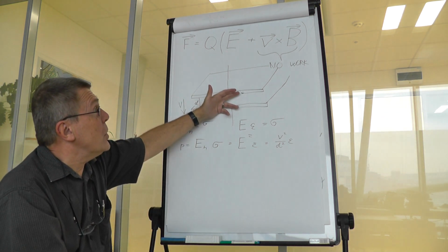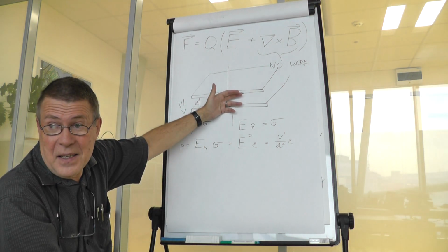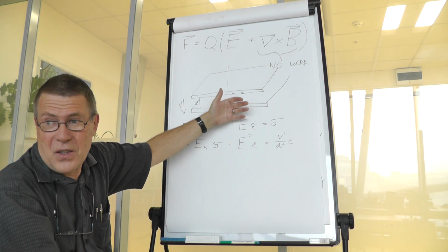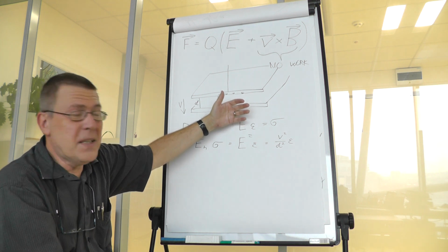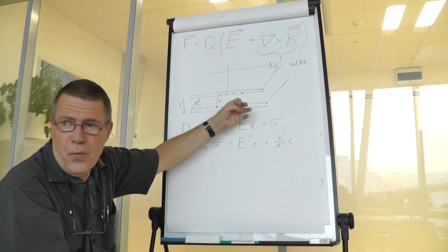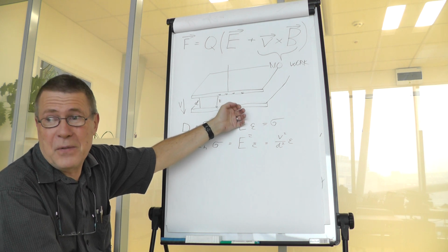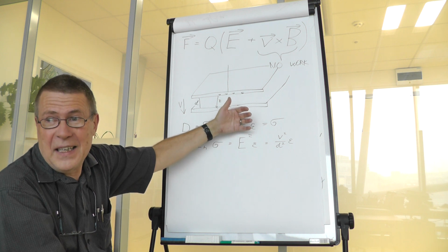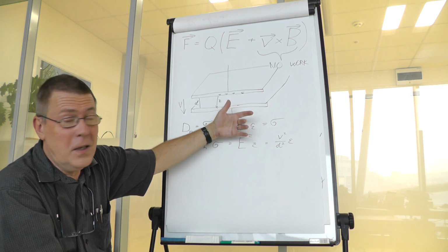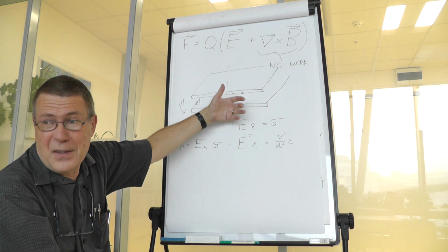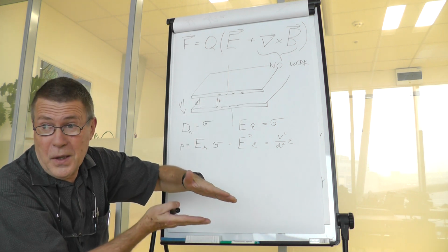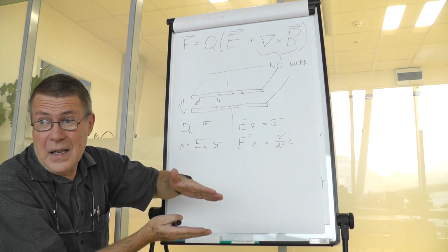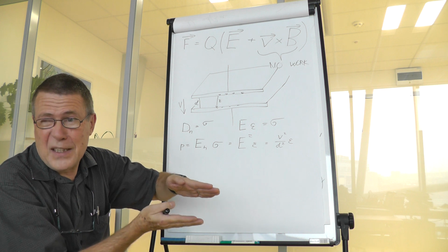But yes, charging the capacitor means bringing mechanical stress into its construction. This would be very low for small signal capacitors, but with high voltages you can get quite a lot of mechanical stress, due to the fact that those two electrodes attract each other, and that pull would increase quadratically with the voltage, as mostly the position of those electrodes would not change.